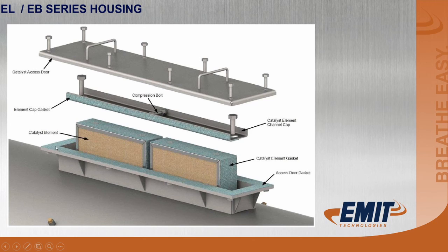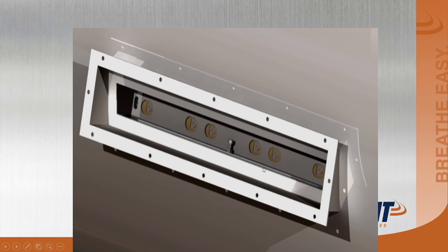Again, on a rich burn engine, it's absolutely critical to have these gaskets in place. I've seen where people don't put the gaskets in, and that allows the free oxygen to build up in the exhaust stream and causes the catalyst not to perform well.